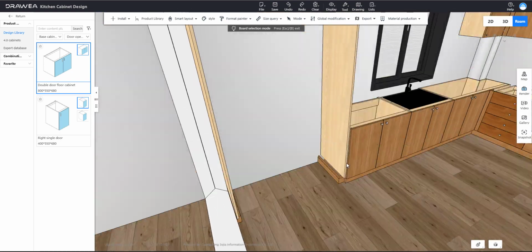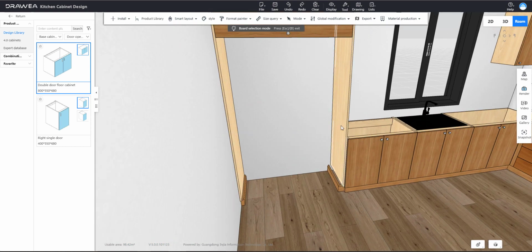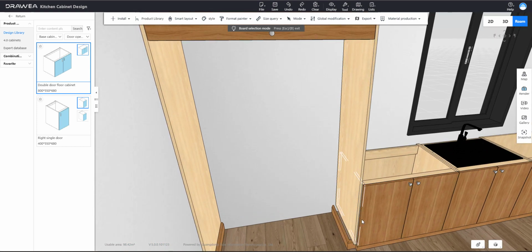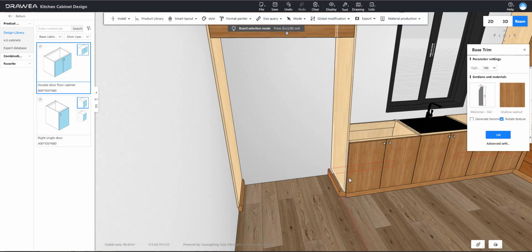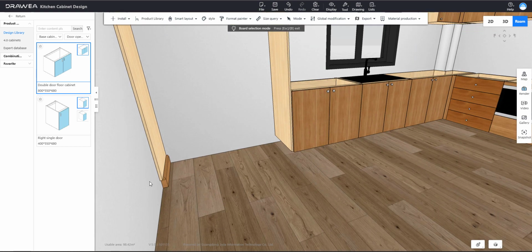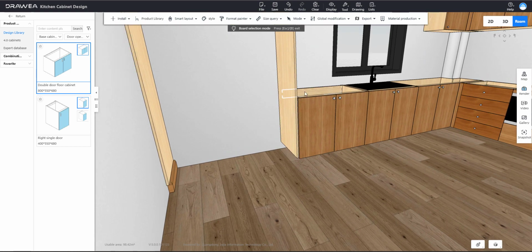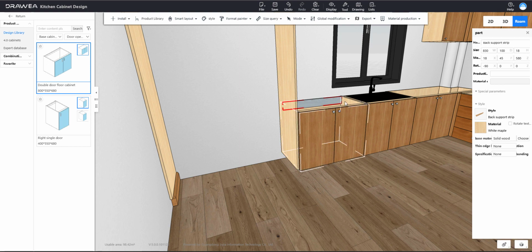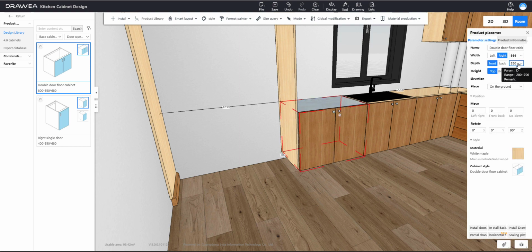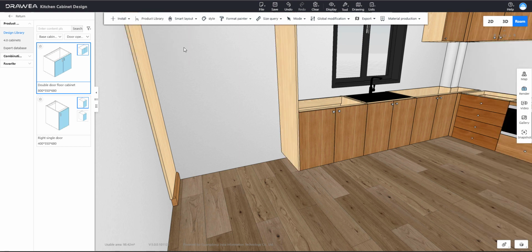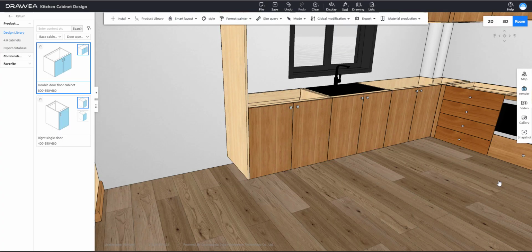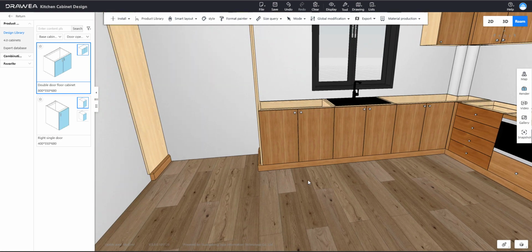Now the depth of the closing element here and the front of the lid don't overlap, so there's a form here that I don't want. I am deleting it again. This time, the depth of this section was 550. My panel here was 520. I extended it to 550, and I click base trim installation again. When I say OK, we see that it forms as a straight line.